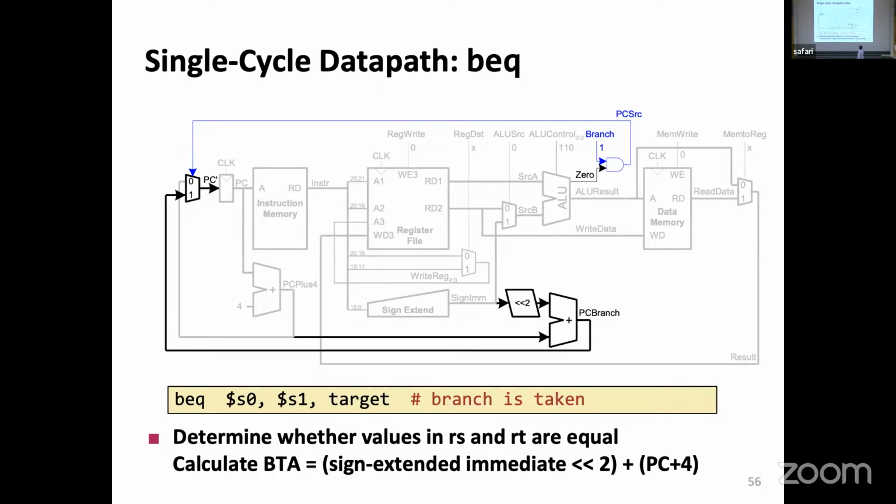I will jump to an address that is offset by the immediate adjusted forward size. And then if the jump is successful, if I'm taking the branch, the program counter will not be program counter +4, but will be this new put together address. PC +4 plus that immediate.